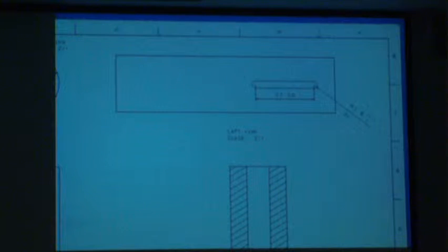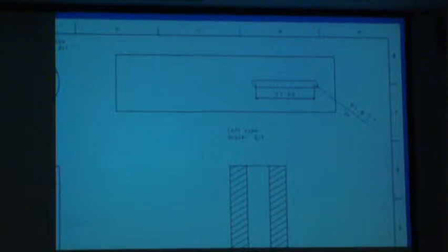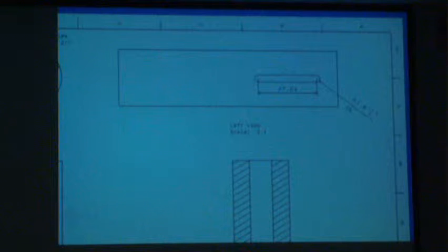Here's the other projection. You can see I've got a dimension for the length of the slot. I've got 2x next to the radius dimension to tell you that there's 2 radii. Now the mistake that I made here when I drafted this is that this slot right here isn't dimensioned to either end, so that slot could drift in and out, and my print wouldn't specify that that was incorrect. So you have no way to measure where the location of this is to know that you did it right. Okay, so that's a mistake. So things like that you've got to keep an eye out for. Your dimensions on a print should completely specify every feature so that they can't move outside of your intended place. And that's the same thing when you're actually creating CAD. You should have everything completely constrained so that it can't move by accident in space.